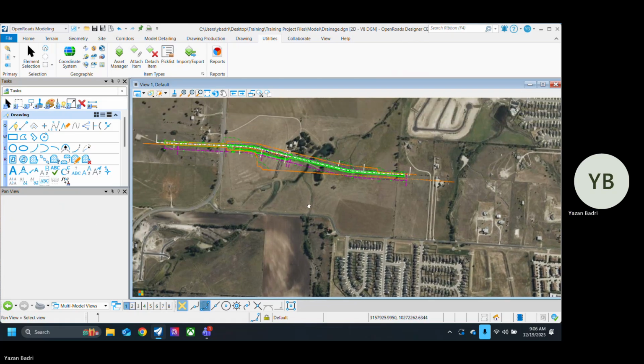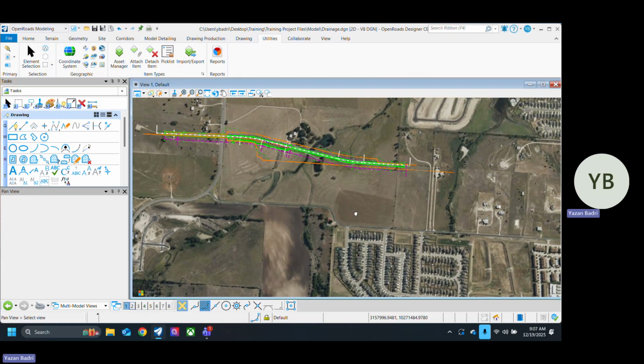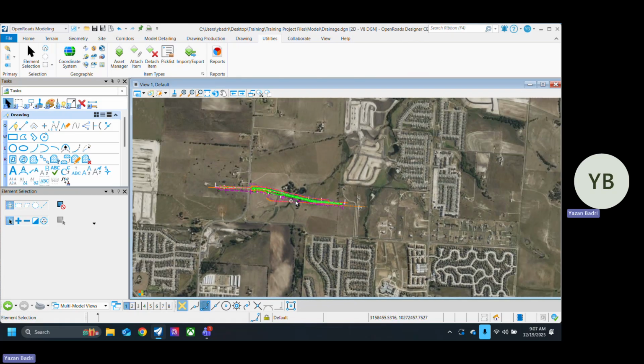Okay. Then what it looks to me like is this is in grid. The area is in grid, but I think the surveyor gave it to you in surface, which is correct, right? So we just need to change the aerial to be in surface rather than grid. We usually use these aerial tiles, yeah. We can do that. Let's try the first one first.